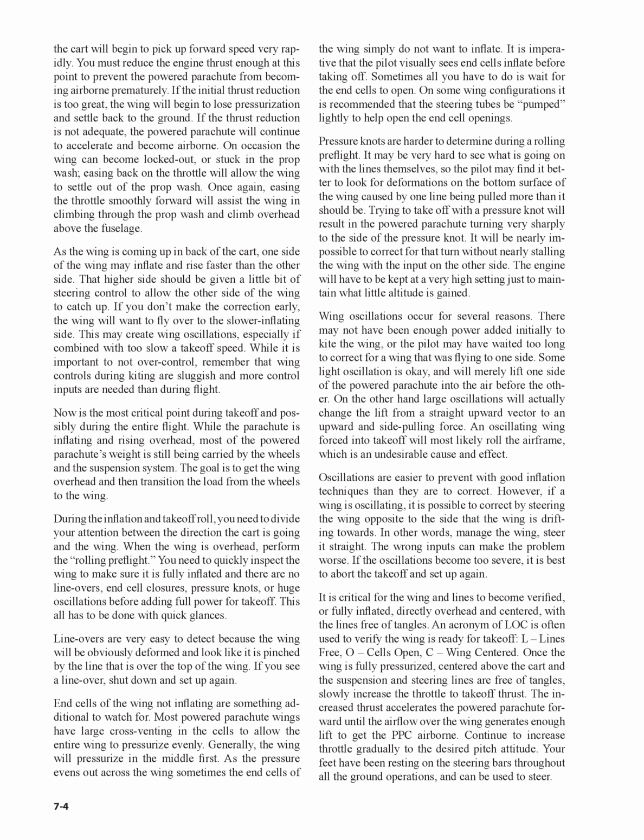It will be nearly impossible to correct for that turn without nearly stalling the wing with the input on the other side. The engine will have to be kept at a very high setting just to maintain what little altitude is gained. Wing oscillations occur for several reasons.